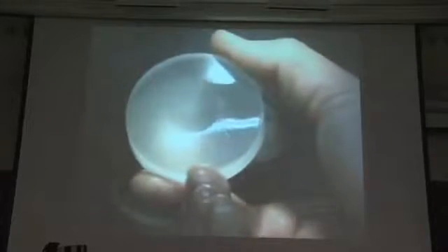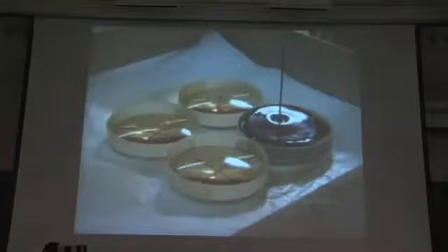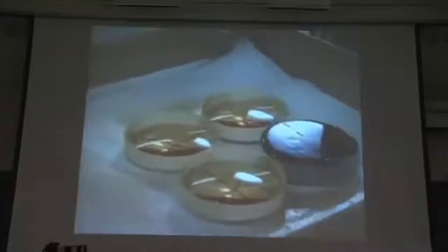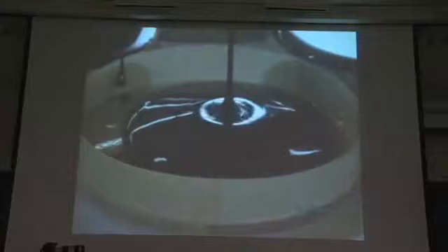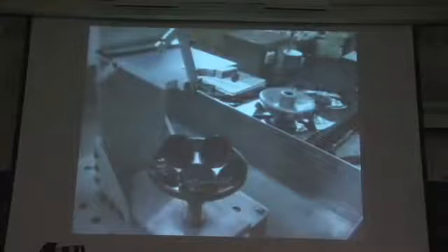The operator checks each lens for chips, and this one looks smooth. This tar-like substance is called pitch. The edges of the lenses have been built up with tape to contain the pitch. They completely coat the underside of the lens with it. Several pitch-covered lenses are now in a metal shell.